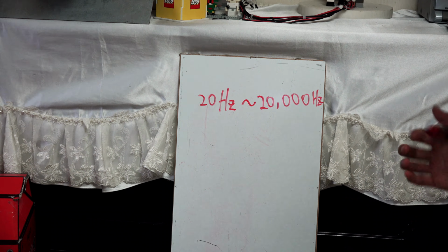So in the loop, many things go on. First of all, it can have some problem if you do not write digitalWrite LOW to trigger, because Arduino has to get the data with this pulseIn, so it must not have anything in before you trigger and get it with the pulseIn.